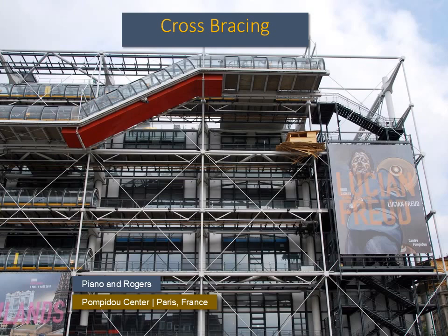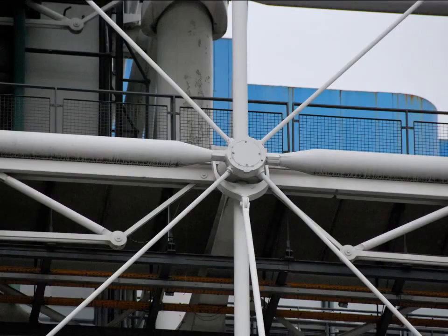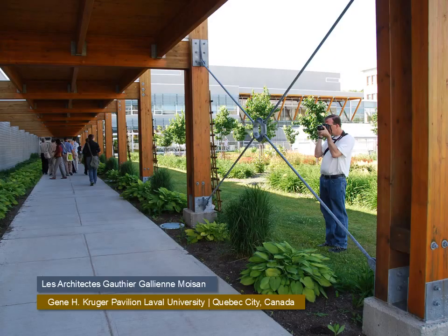The architectural use of express tensile cross-bracing was well established in the design of the Pompidou Center by Piano and Rogers. The creation of the connection detail at the center of the transfer of forces has generated some interesting solutions. Here, the rods are accepted by a section of round HSS with a simple cover plate to hide the bolts in behind. Steel is often used to brace timber structures, as in the case of this exterior walkway.